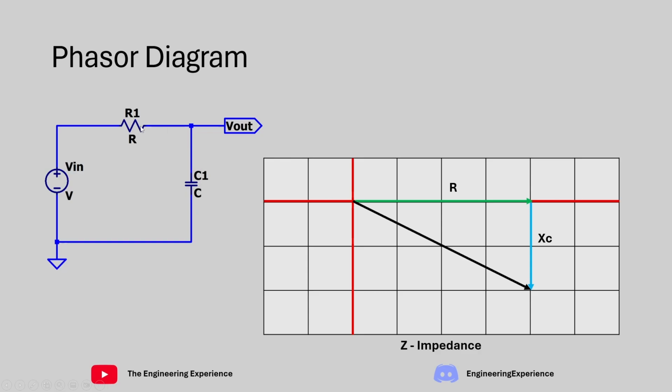You can imagine this as a potential divider with a resistor that varies with frequency. With high frequency you get a very low resistor here, and with low frequency you get a very high resistor here. With a high resistor, most of your voltage drop will be across the C, and with a very low resistor, most of your voltage drop will be across the R, which the load won't see. So this circuit protects the load circuit from any high frequency signals that are present, be that noise or anything else.